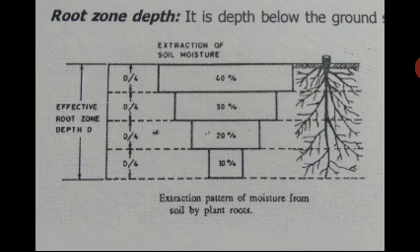Moisture equivalent. It is defined as the percentage of moisture retained in an initially saturated sample of soil 10 mm thick after being subjected to a centrifugal force 1000 times gravity for a period of 30 minutes.